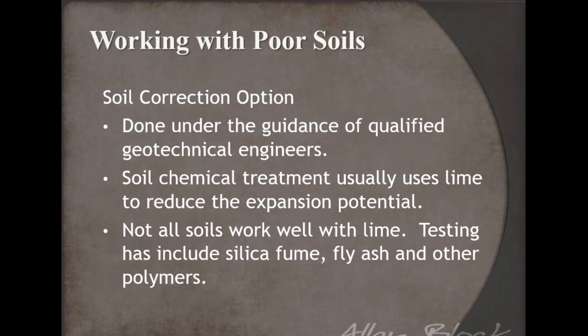If you've got a large commercial site and you've got some questionable soils there, you might be money ahead by getting a geotechnical engineer involved and letting them look at the soil characteristics, and maybe there's an additive that can be applied to the soil. So now the moisture content isn't as sensitive, or maybe it brings it into a workable material. And guys have used even a dry sand, but I've seen them use lime, even some silica fume, fly ash, or even some polymers that have been used.